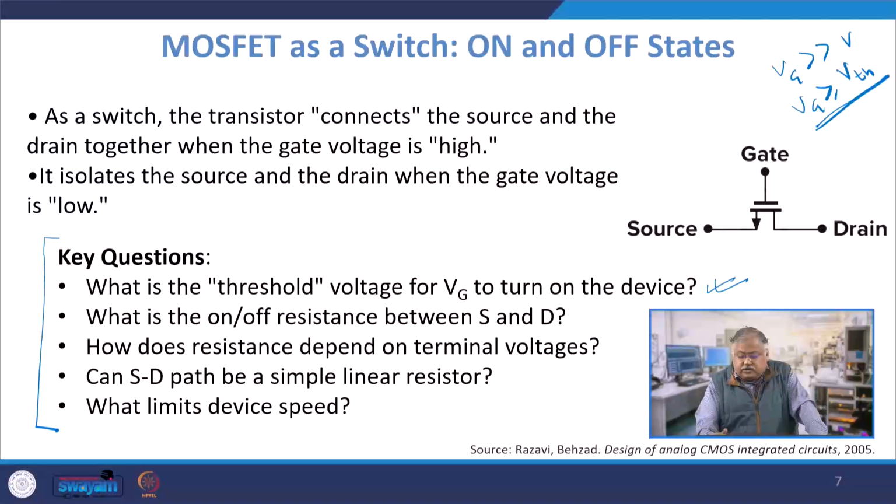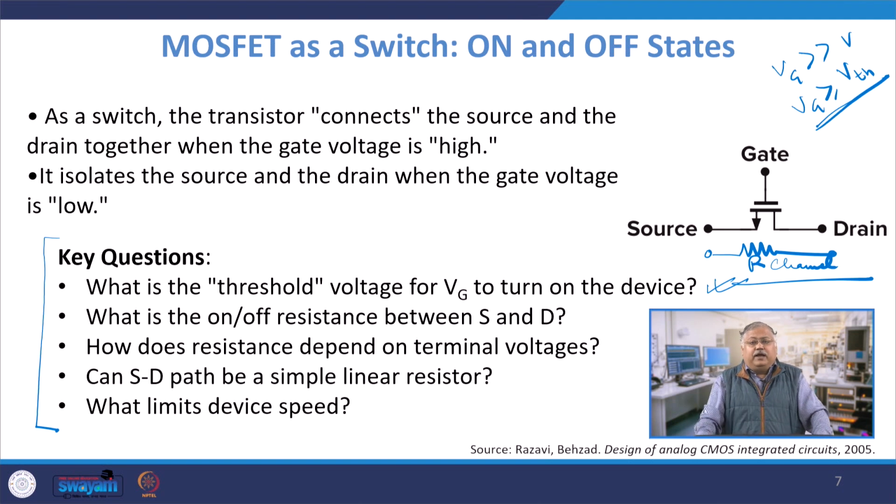Similarly, as the drain voltage increases, the current will increase. These are all very simple and straightforward, right. But we can actually emulate this as a resistor now. Why? Because current is flowing and a voltage is given, so V by I equals R, and that R is basically the resistance of the channel, correct. It also takes into account the resistance of the contact, the source-drain region, the depletion region, and the channel, everything, and that gives you a lumped value of the resistances.